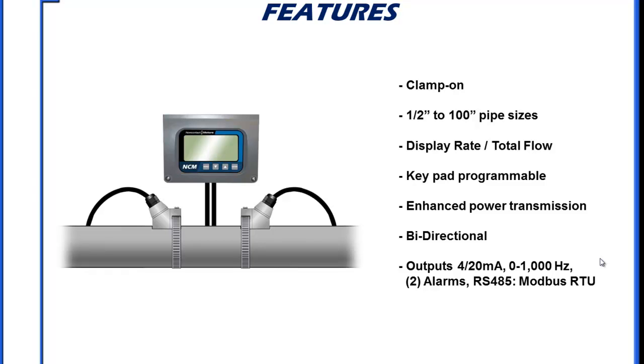The electronics are designed to display flow rate and total, or if you have an energy module, you can measure temperature and BTU. This small little package is new technology, so it has a lot of punch on the transducer output. So in your larger, your cast iron, your nasty applications, although this is a little smaller box, it's more robust than most of the transit time flow meters on the market. And secondly, you'll find that its price point is lower than most devices you'll find. Basic units like $2,200, $2,300 to monitor flow rate and total, and pipe sizes up to 100 inches.